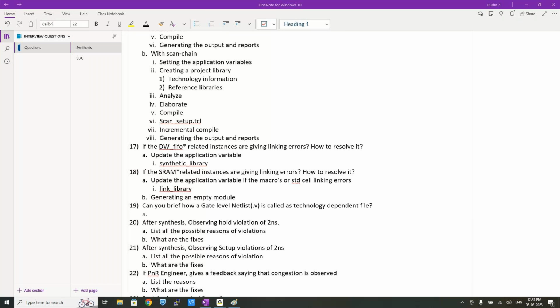The second difference is that the parasitics will change, and the third difference is that the naming of the instances, that means the naming of the cells, will also change. Okay, there are three differences. So based on the optimization inputs which we provide, the tool will try to optimize it and give me a netlist. The generated file will give me better accuracy only if I use the same technology libraries.